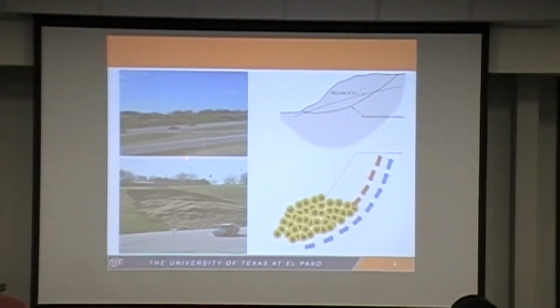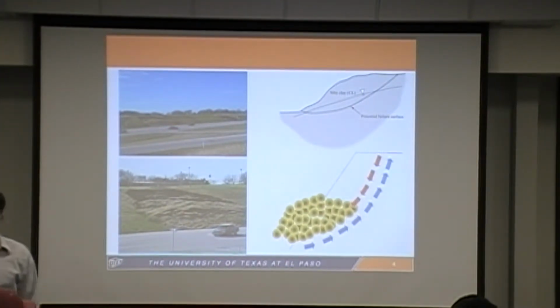So this is a picture that I took in the Dallas area. Notice that we are looking at a slope. That slope is relatively flat, at the right of the highway, right next to the highway there. But still this slope failed. This is what a failed slope, even a very shallow and relatively flat one, looks like. The night before, they had a lot of rain, and that rain essentially compromised those frictional forces. Even on the very flat slope, you see the failure took place.